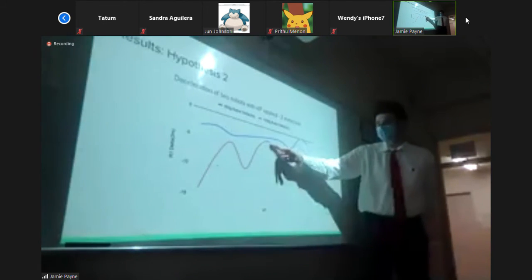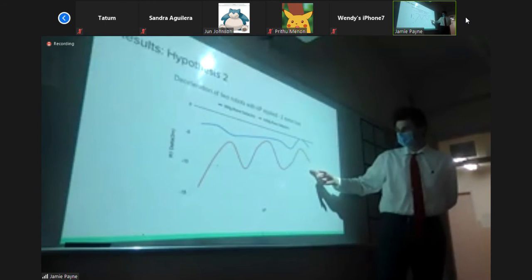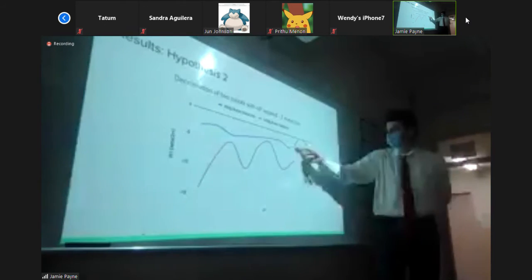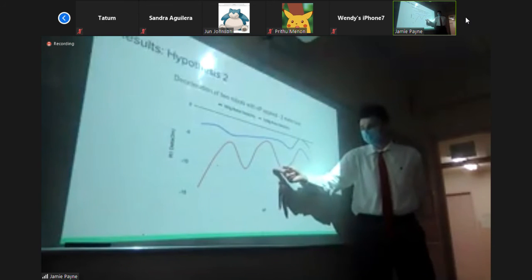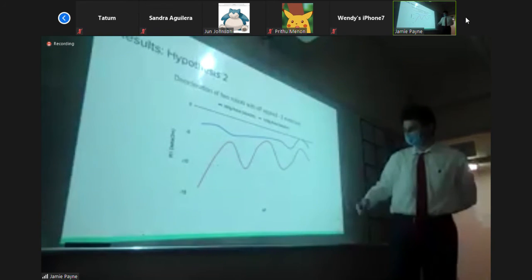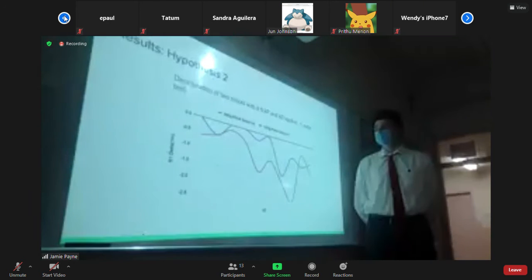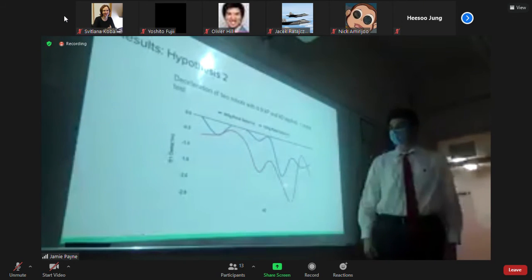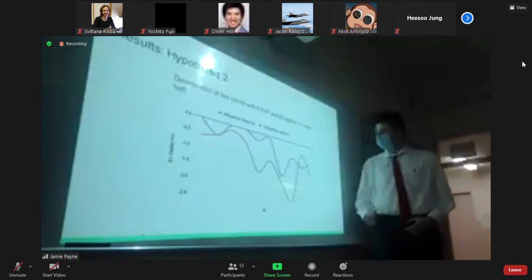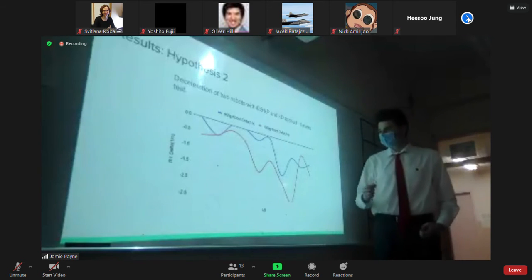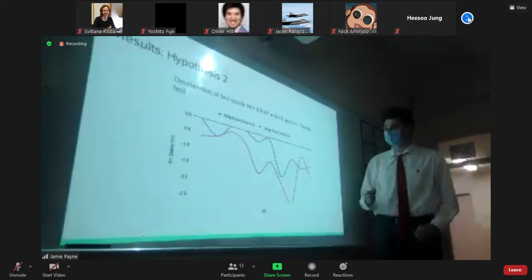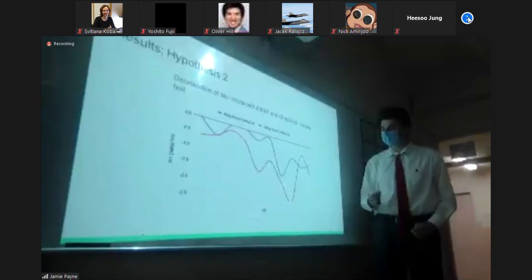I could not identify why this was the case, even though this one seemed to be getting closer, but the 1200 gram robot just kept going all over the place. Then once we put together the derivative component with 0.9 KP applied, this started to really go downhill, literally and figuratively.